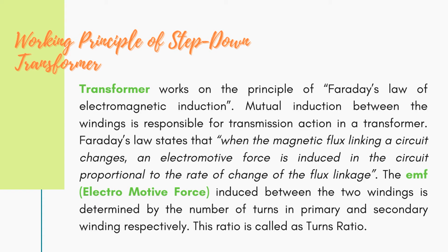Working principle of step-down transformer. A transformer works on the principle of Faraday's law of electromagnetic induction. Mutual induction between the windings is responsible for transformer action. Faraday's law states that when the magnetic flux linking a circuit changes, an electromotive force is induced in the circuit proportional to the rate of change of the flux linkage.